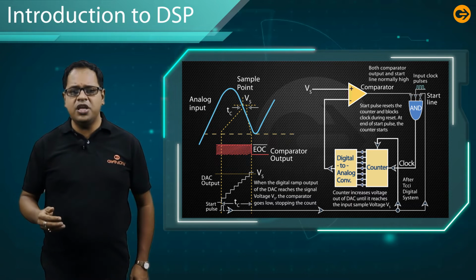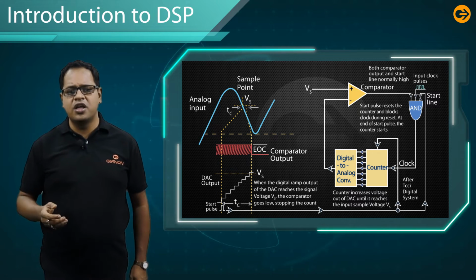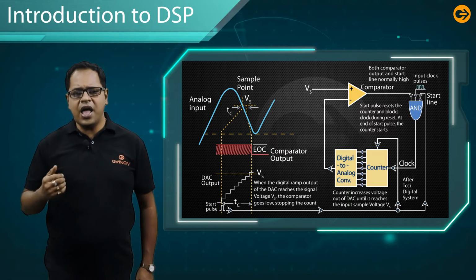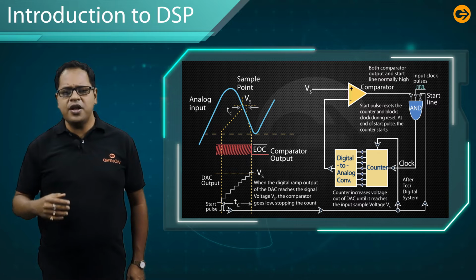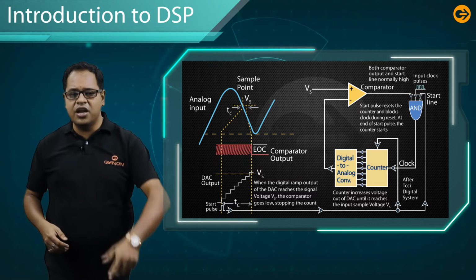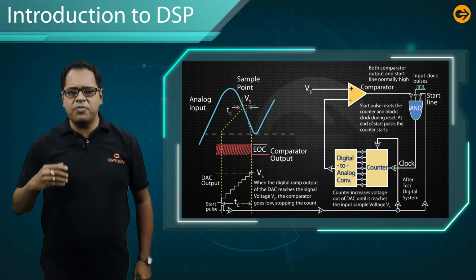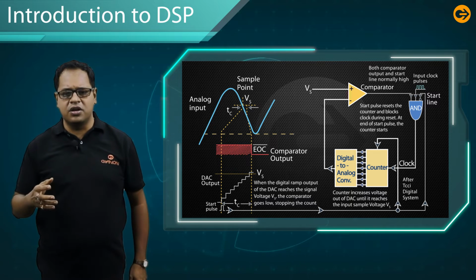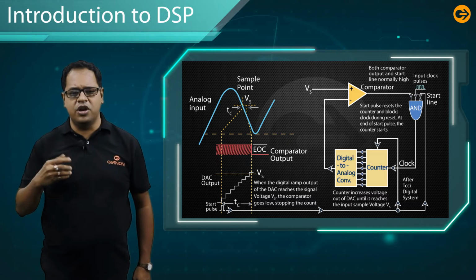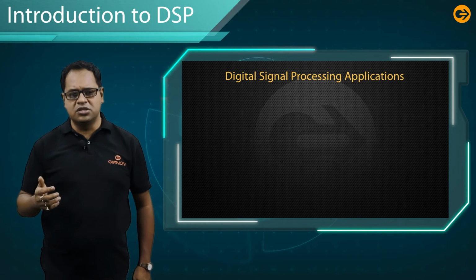One way to achieve this is by applying the analog voltage to one terminal of the comparator and a trigger known as a binary counter, which drives a DAC, while the output of the DAC is applied to the other terminal of the comparator. It will trigger a signal if the voltage exceeds the analog voltage input. The transition of the comparator stops the binary counter, which then holds the digital value corresponding to the analog voltage at that point.